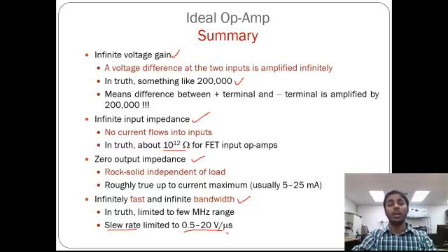We're going to talk again about how to calculate this slew rate based upon the input signal later in the discussion of operational amplifier parameters. In general, it's going to be around 0.5 volts per microsecond. In the last class, I talked about going through the link to the data sheet for the LM741, where you will observe all these different characteristics: the input impedance, output impedance, slew rate, and the bandwidth of the signal. The bandwidth is based upon the frequency of operation of an amplifier. For our IC741 it is limited, usually in the order of megahertz range.